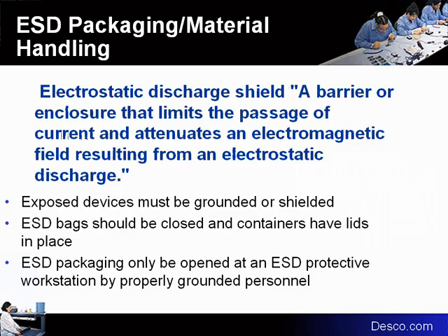The electrostatic shield is what gives the protection from any discharge. When the item is placed inside a metallized bag and the bag is closed and sealed, the operator can then disconnect from the wrist strap, carry it, transport it, place it in inventory, or move it to its next task. But before the bag is opened, it should be at an ESD protected area. The operator would have a wrist strap. As soon as they touch the bag, any charge on the outside of the bag would be brought down to 0 voltage and would be safe to remove the device.